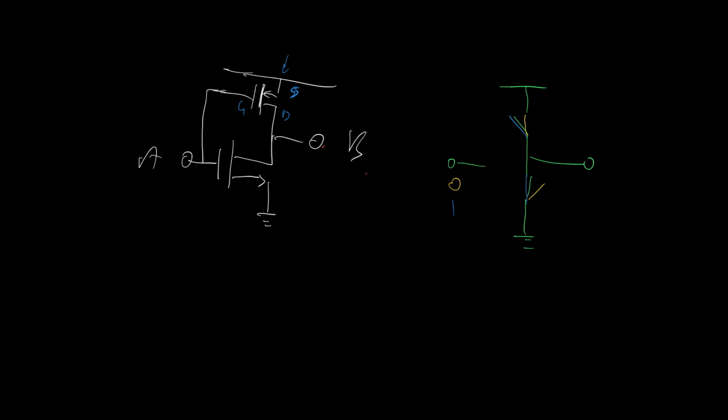So in this case, this switch is closed and that switch is open. So using two FETs, N-channel on bottom, P-channel on top, allows us to form, ideally, this circuit here with two voltage-controlled switches, and whenever the top switch is open, the bottom switch is closed, and whenever the top switch is closed, the bottom switch is open.